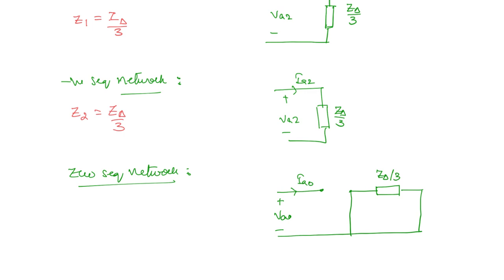So now the question is why we have represented this. Sometimes in the delta there can be circulating currents. In order to represent that there is going to be some circulating current, we are showing a closed loop. Whereas in a star connected load that is not the case; there will simply be an open circuit. Here in addition to the open circuit we are just showing one extra loop. And here there is no significance for the zero sequence impedance. There is no impedance here.